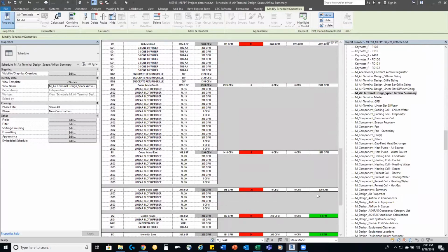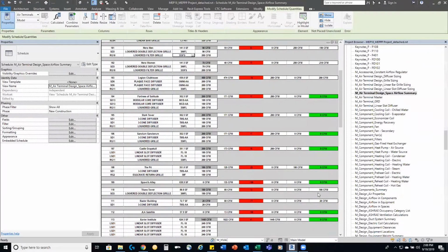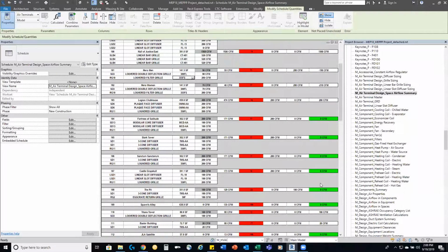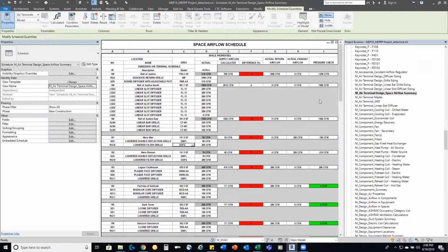What makes this super, super powerful, guys, is that when you combine this with the auto sizing capabilities of the diffusers and VAV boxes, this schedule has literally changed the way that I work in Revit at this point. It used to be my 4-part workflow for success in MEP was to select and place your equipment, even if it's just general, define your logical systems, model your connecting geometry on those logical systems, annotate the model, and print.